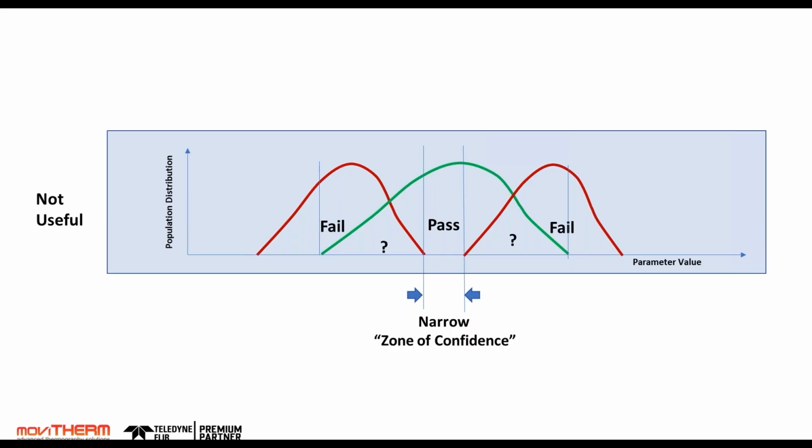The defects are just going to get caught up in the noise of your process variation. So that's one of the key things: when we set the system up and you start looking at hundreds, thousands of bottles, you're going to get a good idea of the process variation. A lot of times you can make adjustments to maybe the torquer or the capper, or maybe it's the line speed. There are just so many variables that you can tighten up to get that bell curve as sharp as you can.